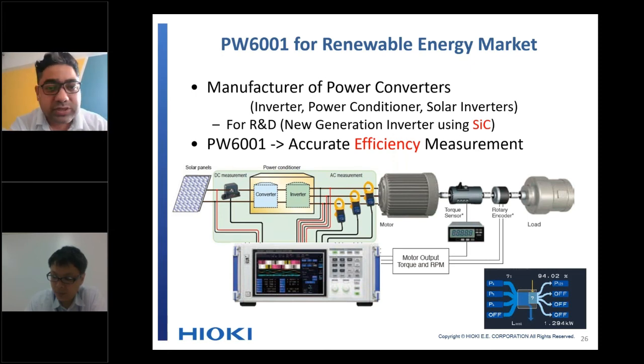The question can arise: if I open it, then we are losing power. Yes, that's why we are saying there is no need to do the test in sunlight. You can even do the test at night, when the solar power plant is not generating anything, right? But you need to open it, because the bypass diode tester is injecting current. If we do not open that fuse or isolate our string from your circuit, then the current can flow in another direction and the testing will not be done properly. So it is always better to open that string from the circuit, right, Sagada-san? Yes. Thank you.